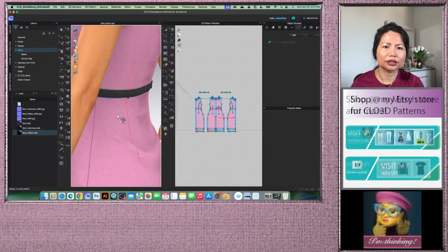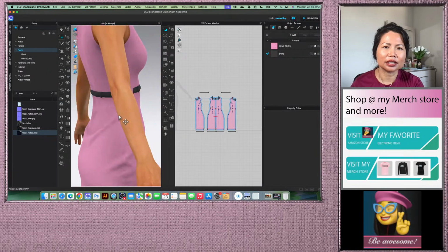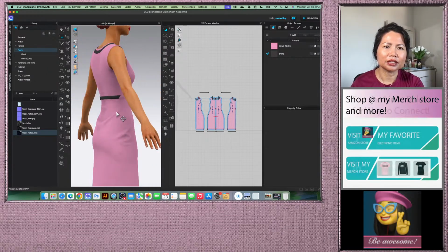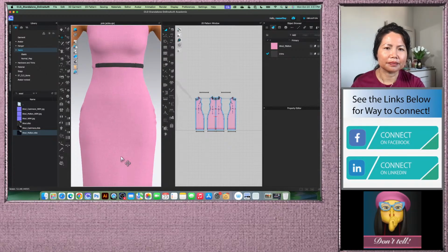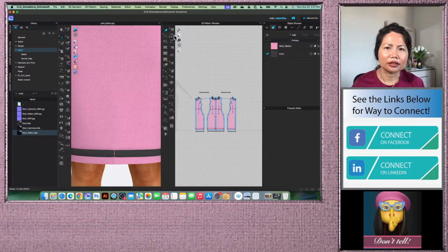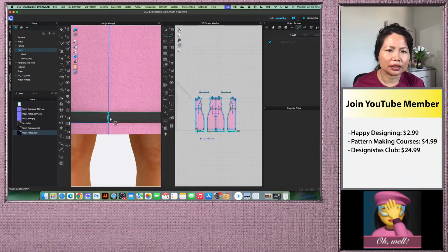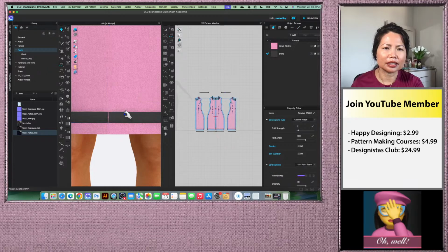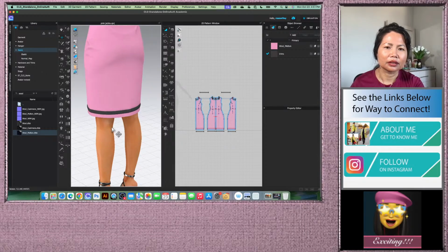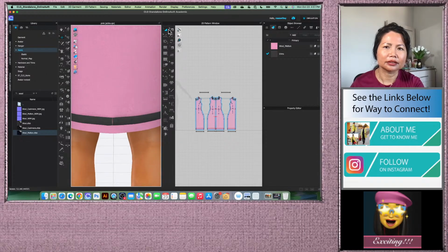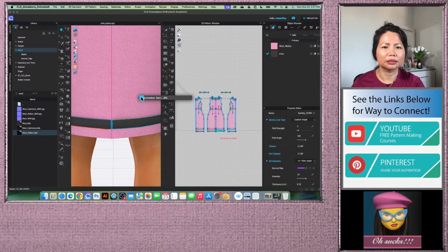and again. So the dot area, we have to fix that problem, which either we can decrease, and how about particle distance here a little bit. Okay, we also need to sew the front. So segment sewing tool is perfect. Okay, I'm going to simulate here. Perfect, actually looks pretty good. Also in the back. Right there, simulates again.